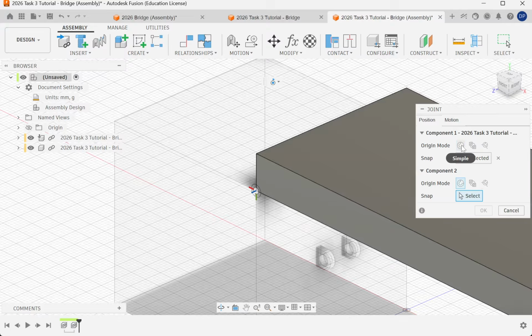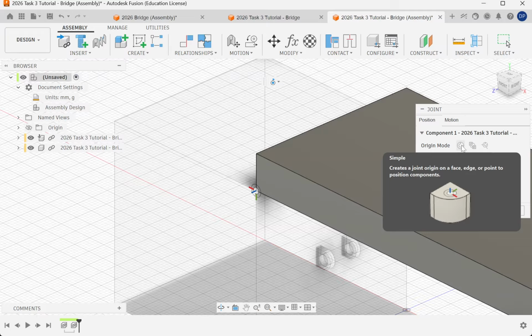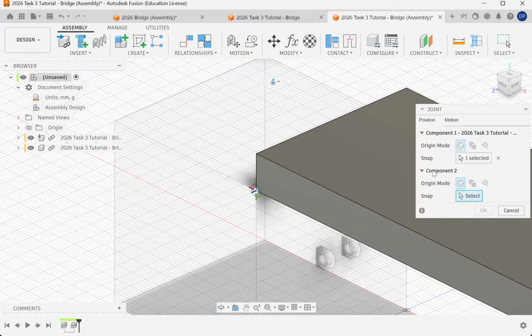As soon as you select the body, it will automatically hide it for you. So that's convenient. Now it's saying, all right, you can't connect an object to itself. So I've hidden that. Now, every other object, what do you want to connect it to? Well, I want it to revolve around this corner over here because they're overlapping. So I'm going to do the same thing.